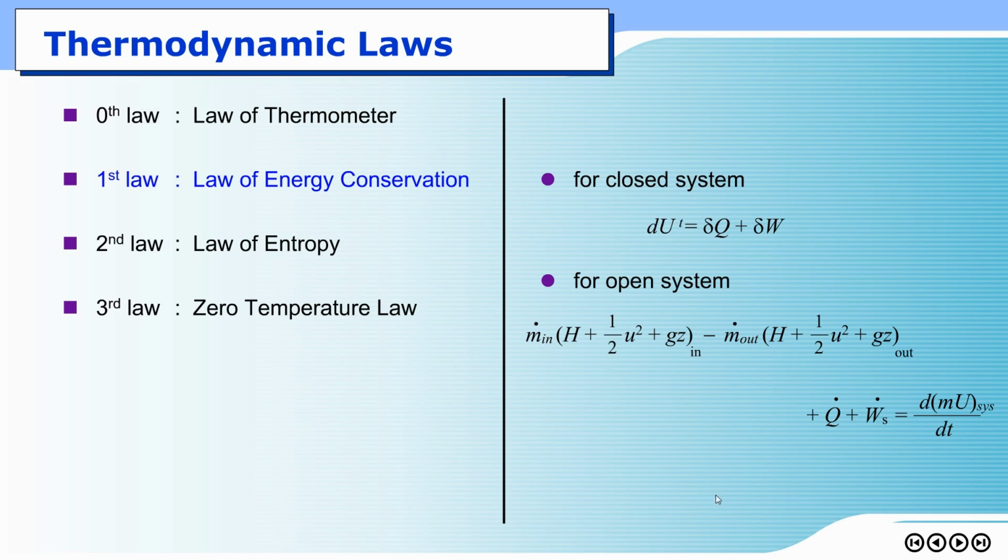In closed system, on the left-hand side of the equation is essentially change in energy. Now we focus on the internal energy only. But if you apply the first law of thermodynamics to general problems, you should include kinetic and potential energy as well. Again, the left-hand side, d, means change in energy.